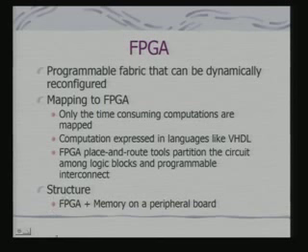So, when you are writing a computation in VHDL, it comprises a set of functions. Now, this set of functions has to be again partitioned and mapped into the FPGA blocks. For that, we need to use what we call place and route tools for partitioning the circuit, which you can synthesize from your VHDL description of your computation to different logic blocks on the FPGA.